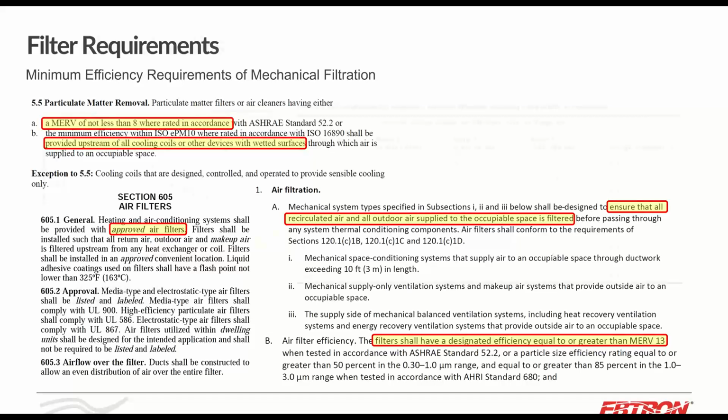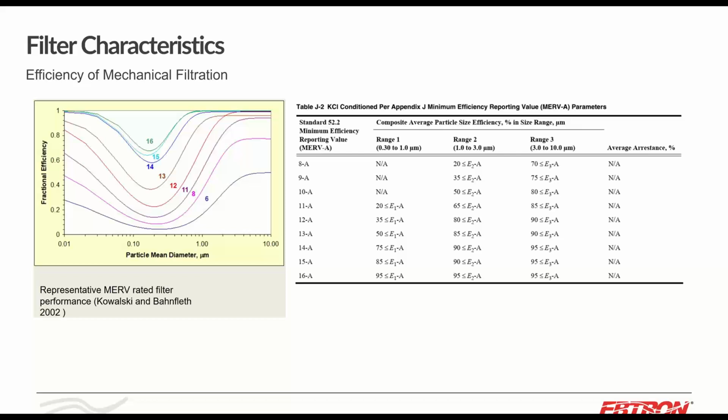So when we're looking at the mechanical filters, this is the shape of the curve. When we looked at COVID-19 or the SARS-CoV-2 virus, the virus particle size was 0.10 microns, but the virus itself didn't travel naked through the air. It traveled in with your moisture from your mouth, whatever is in your spit, and some other proteins that are mixed together. So it's a little bit larger. But you can see why there's a recommendation for MERV 11 at a minimum, or MERV 13, because it does a very good job of removing smaller particles in the range of 1 to 3 microns.